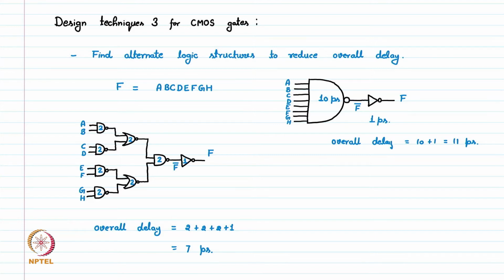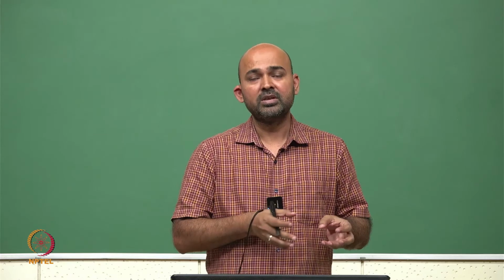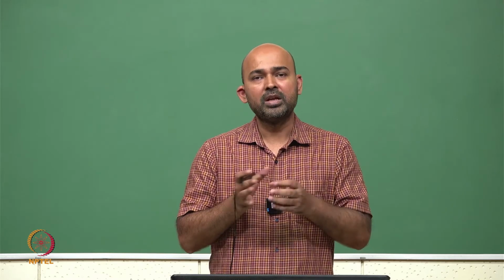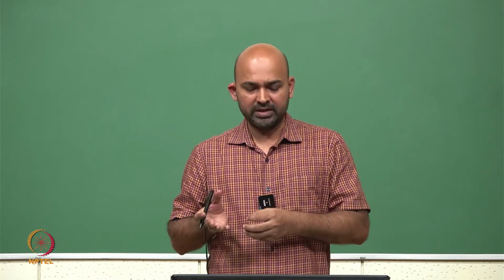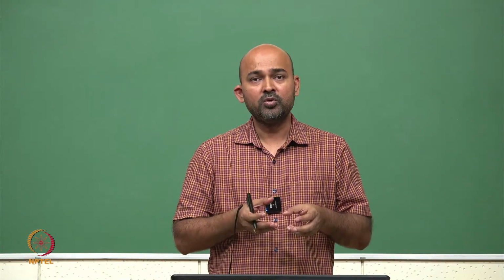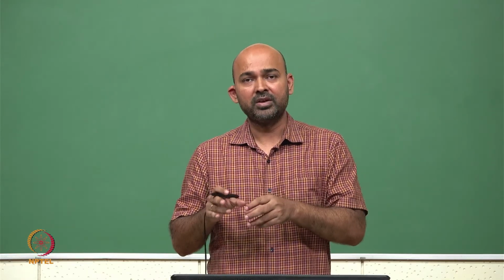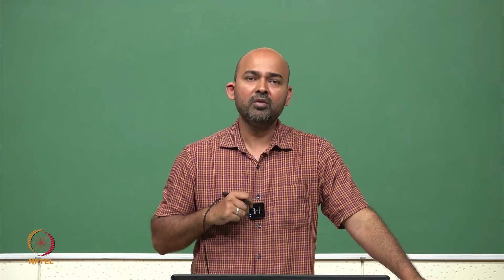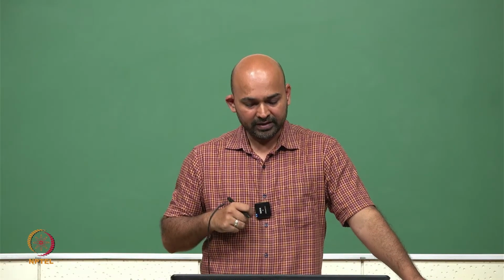So here we have seen some design techniques through which we can optimize the delay of a logic gate. For example, Boolean algebra, which you have to apply on the implemented function and simplify it in such a way that the overall delay is less, or we can do ordering of inputs. So that technique we saw.